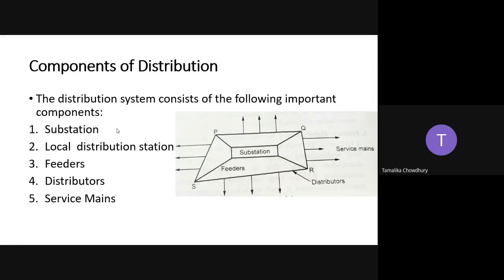Okay, so no tappings are taken from the feeders. The feeder current always remains constant. The voltage drop along the feeder is compensated by using compounding by generators. Some of the distribution generators are used there.